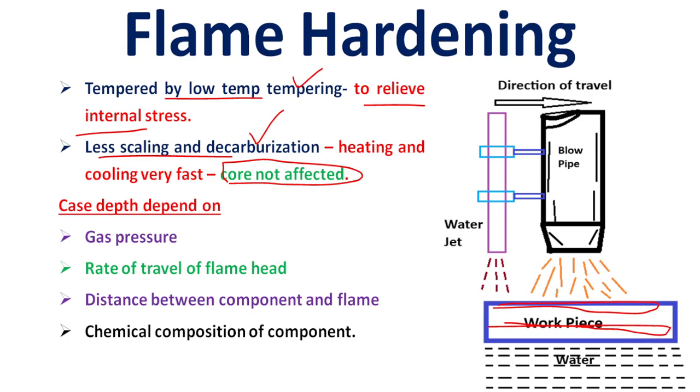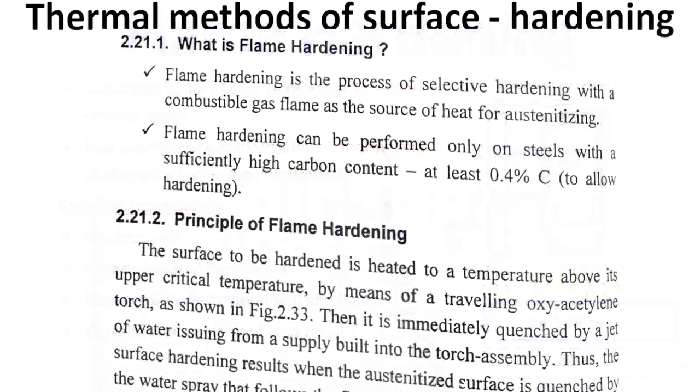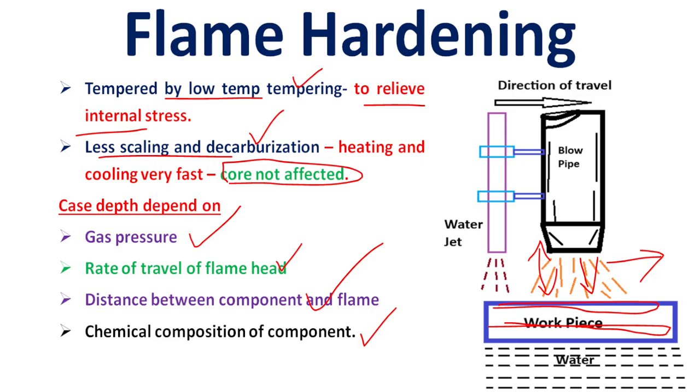The case depth mainly depends on the gas pressure, the rate of travel of the flame head or component, the distance between the component and the flame, and the chemical composition of the component. This is the flame hardening process. Thank you.